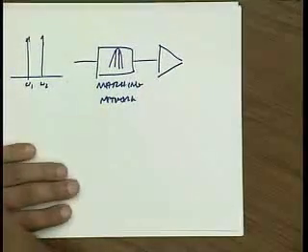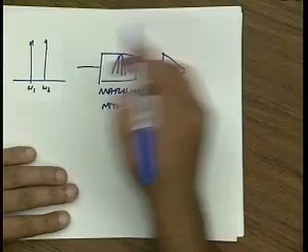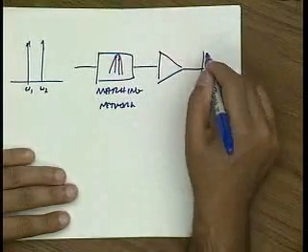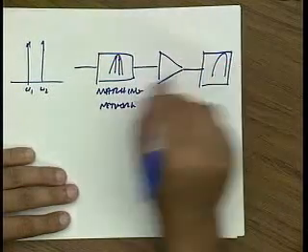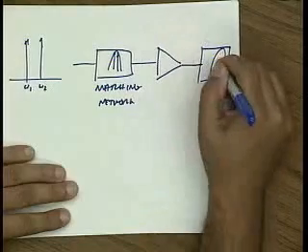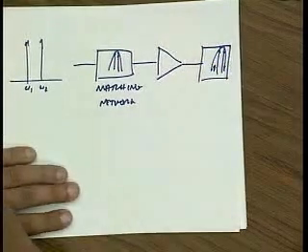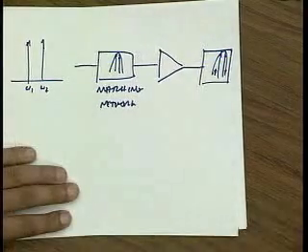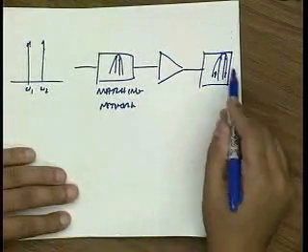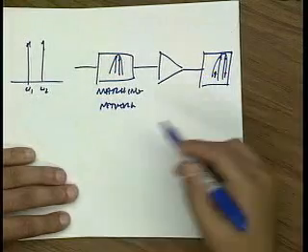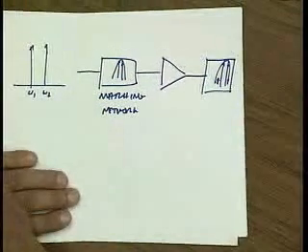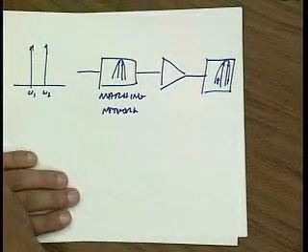Then we go into our amplifier, let's say it's a FET, it generates all the distortion products, and then there's another matching network. And that will filter out all the distortion products except for the cubic, pentic, 7th order, 9th order intermod terms which fall in band. The other ones get attenuated by however much the filter attenuates those. Okay.